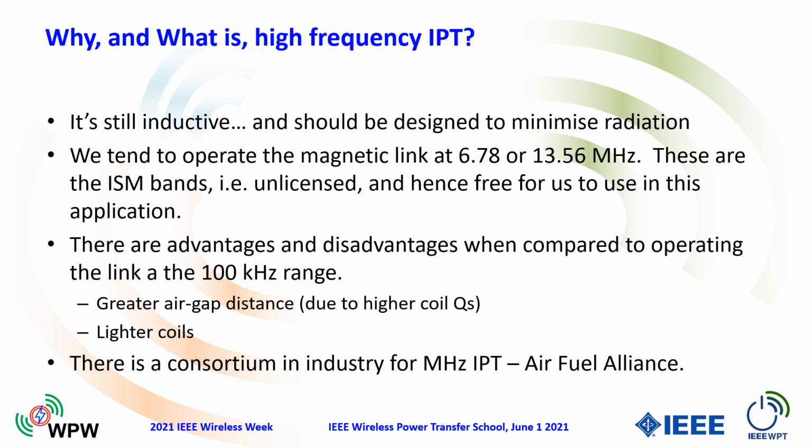So just to put some bounds on this, what is high frequency IPT? I mean, to an extent, it's all reasonably high frequency because all of the inductive power systems that you see, including the ones you may have on your mobile phone, the Qi standard and the SAE standard for charging of electric vehicles, they all work at reasonably high frequency. Those ones are typically operating at something like 85 kilohertz. Although in my world, we refer to that now as low frequency IPT, the kilohertz, the tens of kilohertz, 100 kilohertz type of operation. We refer to that as low frequency IPT, even if it's still a reasonably high frequency in the power electronics field.